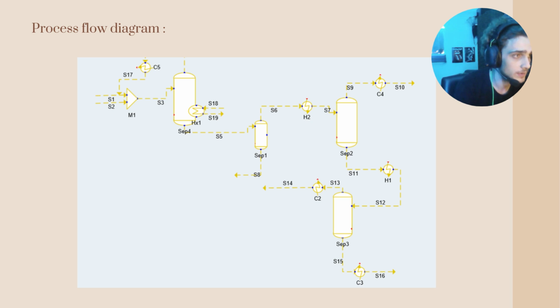After the liquids are heated to 77.8 degrees Celsius, they enter the distillation column, and the ethyl acetate turns into vapor and escapes the column by the top and is cooled by C4. The rest is liquid, so formic acid and acetic acid are liquid, and they go out of the bottom of the column. They are heated by H1 to 100.8 degrees Celsius, and enter the second distillation column.